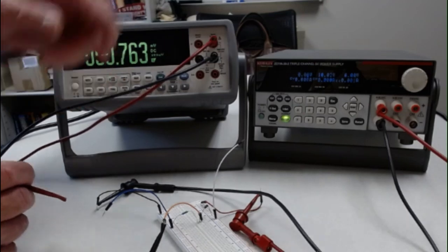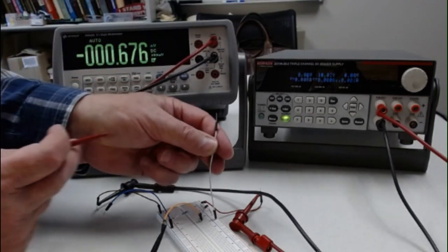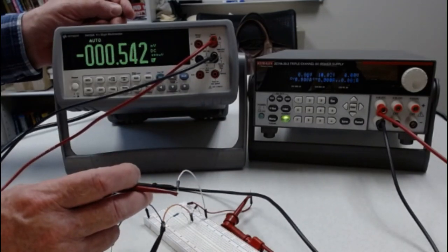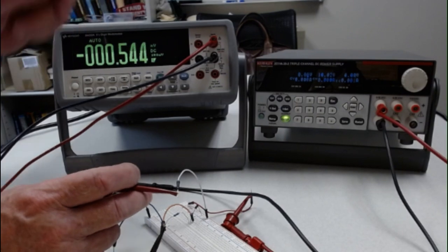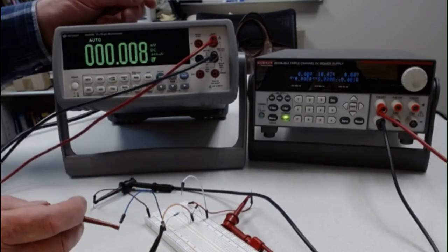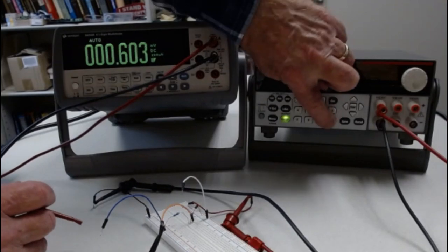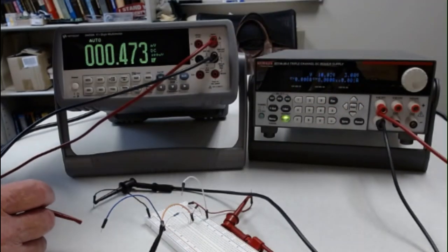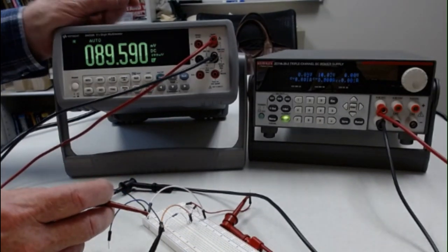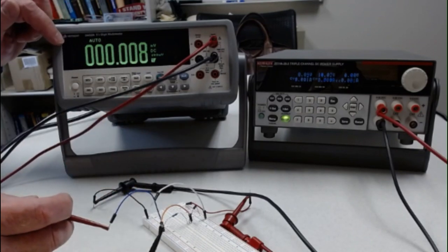So here we go. We're at 0 volts on the A scale. We're going to measure the voltage now across the diode, and it's a little negative, but there it is at 0. Voltage across the resistor. Okay, now we're going to go back and we're going to go to 0.1, enter for this voltage. Voltage across the diode. Voltage across the resistor. Ignore the minus sign if there is one.